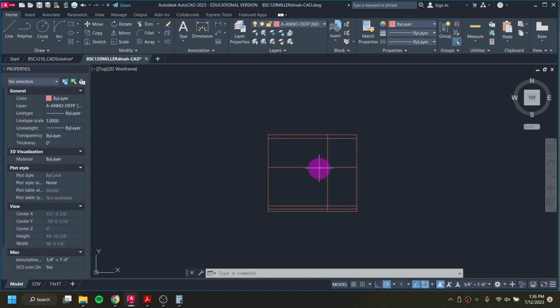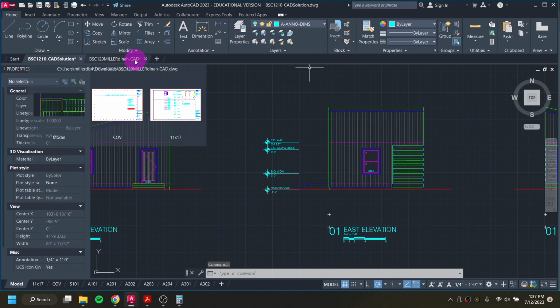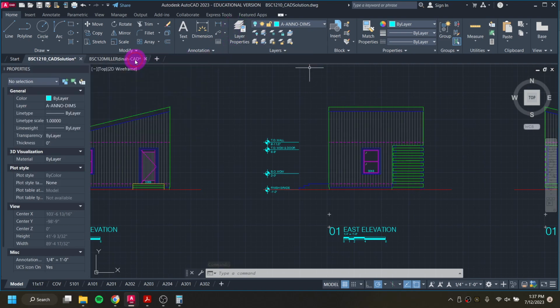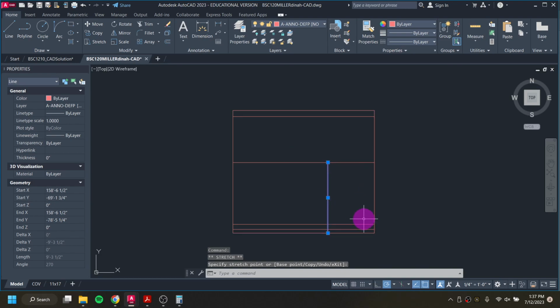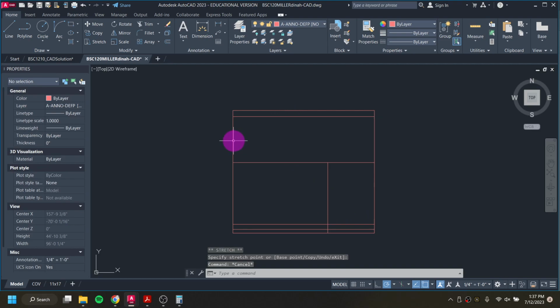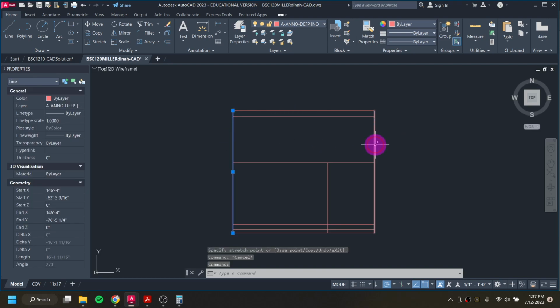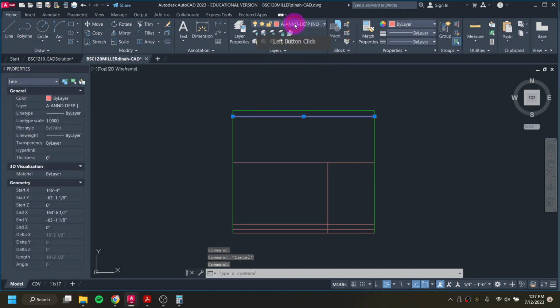So now I've got a little bit of cleanup work to do to make this into my drawing here, but not really all too much, which is fantastic. So I'm going to just shorten this line down to here for now. That's not where this line ends, but that's where I'll shorten it to. I'll switch some of my layers around, so I know that these three are going to be in my green layer, my medium. This one is going to be in my blue layer, my light medium.